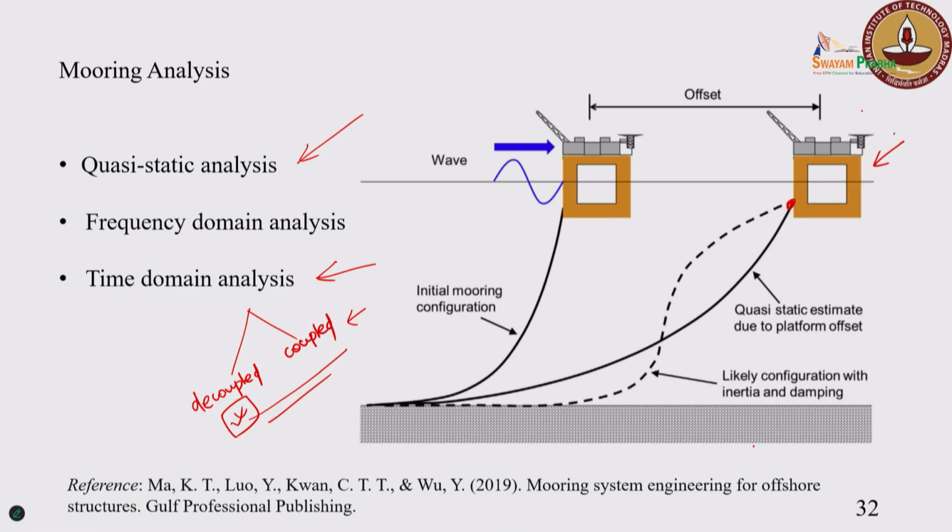Without any moorings, you do the hydrodynamic analysis, and then you feed it to the system, saying that for a given wave the floater will behave this way, and then you go on to connect your moorings. In reality it is not the case, they are all a complete system, correct, but we are separating them. We deal with the floating body separately, and you give that hydrodynamic behavior to the structure that you are interested in, right?